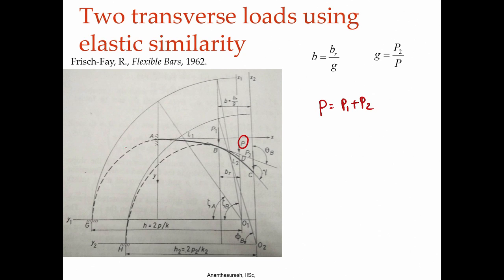For this portion, for this elastica, let us call this, there is a modulus p1. For this elastica, there is a modulus p2, because the rest of the portion behaves differently, because this one is just a transverse force and a moment. This one is only a transverse force from here to here, another elastica. For this one, we know the final angle phi is pi by 2, whereas for this one we have to find phi b. So, corresponding to each force, there is a p modulus that is not known. Except for the last one, this phi end will not be known.